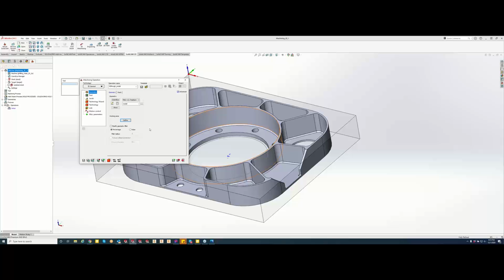So with that being turned off, 3D iMachining is going to look at the stock versus our SolidWorks model or target and machine everything off in between. Now, the cool thing that they have built into this is full fixture detection. We can tell it to stay away from a fixture by a specific value. We have full tool holder collision as well, and it's not going to shank out or run out of flute for you. So it is definitely the easy button for machining.